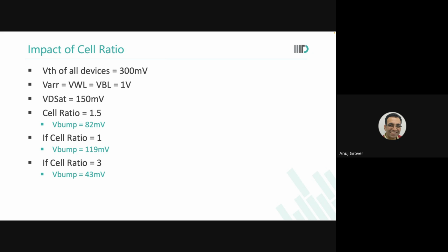It is a lot of area lost, and the gain in stability is also not much. And on the lower side, as we discussed, we are putting in a lower value because FinFET demands that. Otherwise, 1.25. If you're not in a FinFET technology, 1.25 is still something you would want to maintain, not go lower than that.